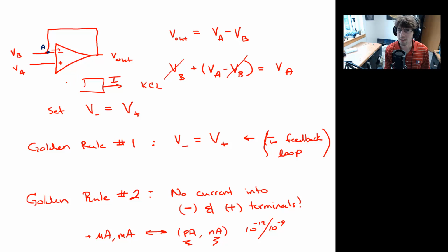So that's a second thing to be aware of: you can have an appreciable amount of current coming from the operational amplifier, but no current going into the inputs. The excess, where does that extra current come from? It is coming from the power supply of the op amp. Go ahead, think about that for a second. Make sure, convince yourself that that's okay.